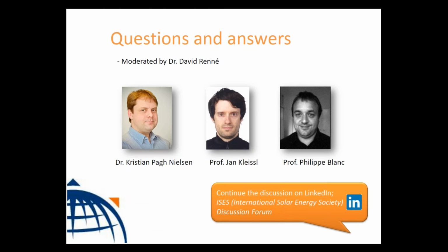Well, I could refer them to NREL, I think Aaron Hapter is working with this. I haven't worked with these because these are specific NREL products. TDY is a typical meteorological year where you only weight direct normal irradiances, as I've understood it, and TGY would then be a typical meteorological year where you only weight global horizontal irradiance. Whereas the TMY, the typical meteorological year, you would then weight a lot of meteorological variables like temperature and so forth. So that's the difference.